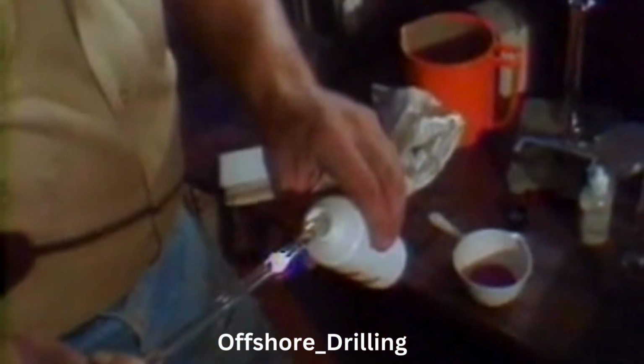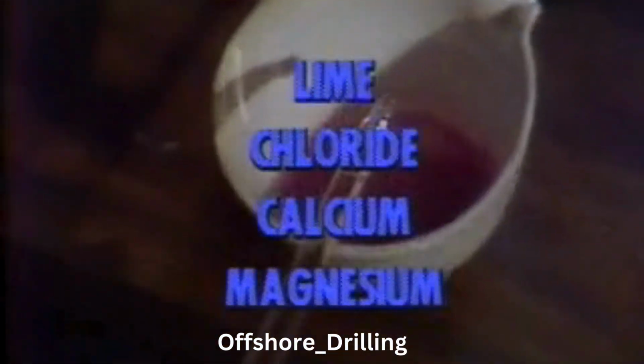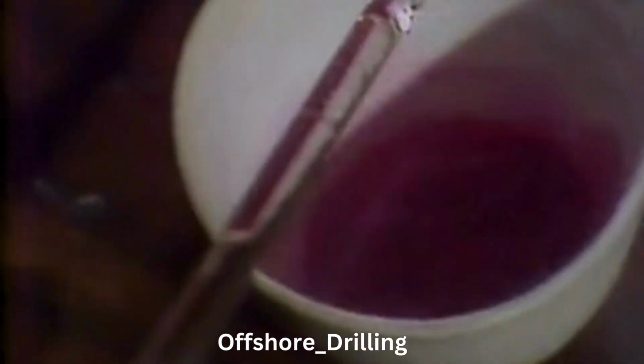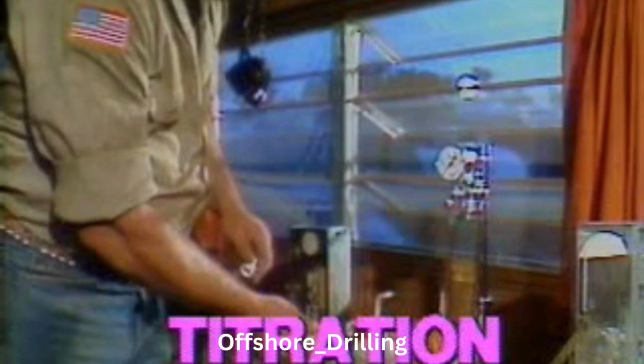The filtrate and mud are tested for their content of lime, chloride, calcium, magnesium, and other things. We use .02 normal sulfuric acid and titrate the red color back to its original state. These tests are made by using chemicals and a system known as titration tests. They're all done with chemicals and are measured by their chemical reactions.